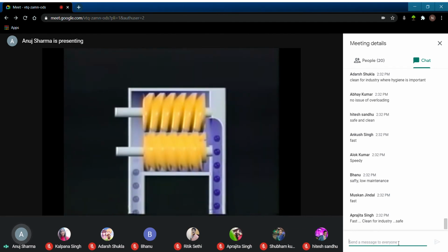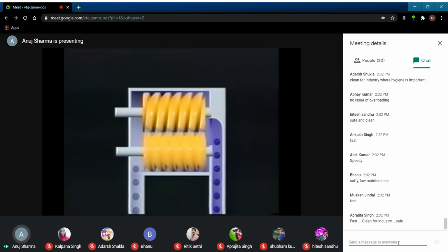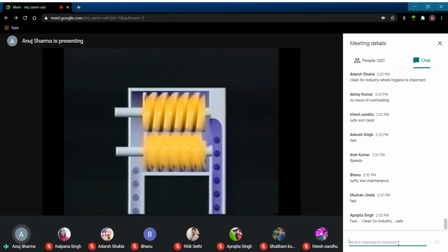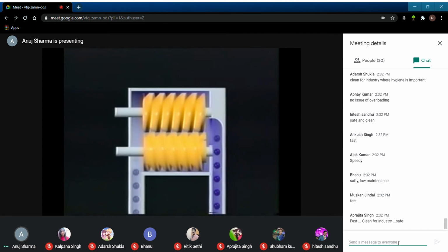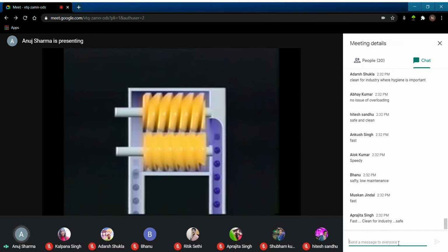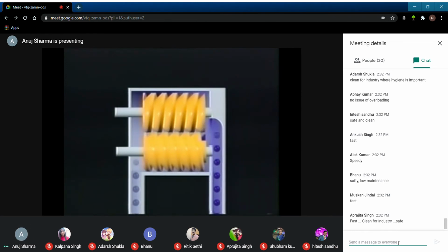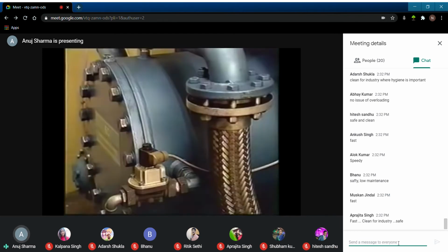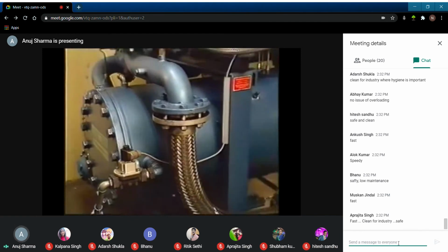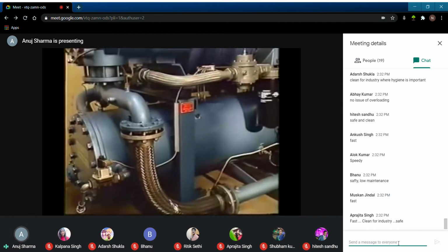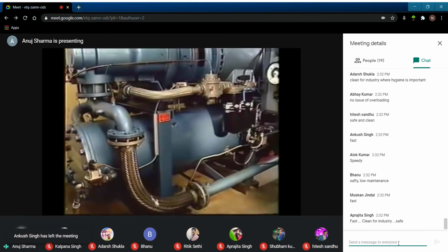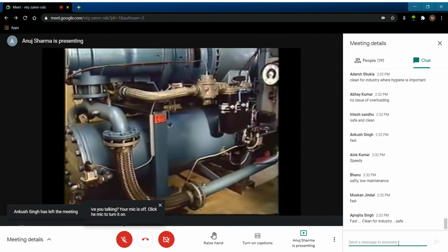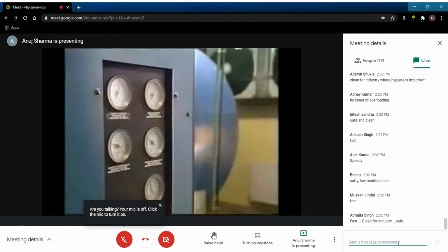The screw-type compressor consists of two threaded shafts that are intermeshed. As they turn, they transport air from the intake side to the compression side. One advantage of this type of compressor is that it produces a continuous flow of air. In both types, as the air is compressed, energy in the form of heat is concentrated in a smaller space. So most compressors include a cooling unit to reduce the temperature of the compressed air. Such units can also be used to reduce moisture, oil, and dirt in the compressed air.